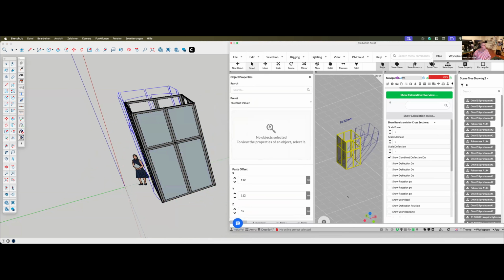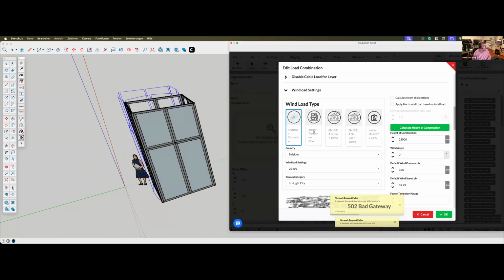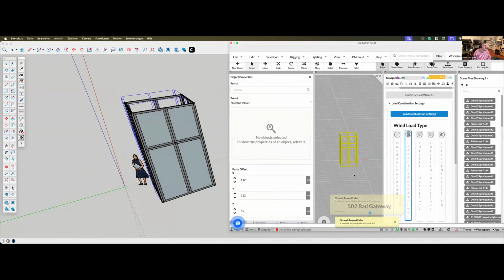So now it's pushed to the side. What we've been using so far is the option that's still using the wrong wind load. We want to do this with the indoor trade show floor, pressing OK. And then it's not overloaded. So then it's at 84% in here. So that's all good. We now need to calculate the ballast for this.